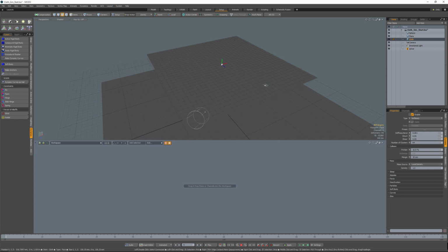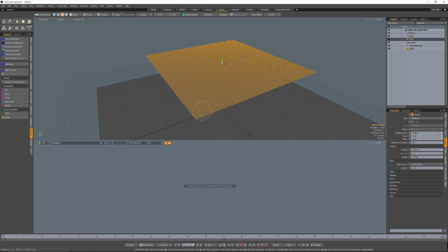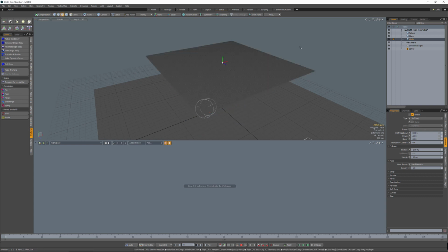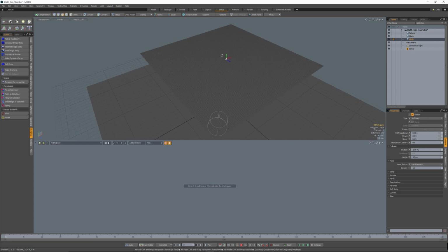And I'm going to up this again here. So let's go ahead and Shift D again. And now we're looking at 4,096 polygons, whereas at the onset we were only looking at 512. And then I'm going to do this one more time. Shift D. And so now we're looking at a fairly dense mesh. And now watch what happens here. I'll go to a top vantage point. As the cloth starts to hit the sphere, we'll start to see these little subtle secondary wrinkles play through. And that's kind of what we're looking for. And that's what adding this kind of resolution is going to help with.